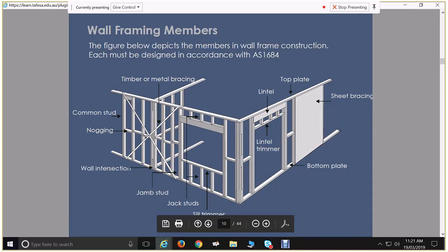Beyond that, then we have our bracing, and we've got two types of bracing shown in this. One of them is your galvanised iron strap bracing. You can buy 30 metres of that for about $10. So it's really cheap stuff to buy, a little bit time consuming to install, because you put it over the top, shoot some nails in, and then you put it down the bottom, and then take it over the top, shoot some nails in. While you're stretching it, you put your claw hammer in, you stretch it over to get a bit of tension in it, and then you tension it up with your little tensioners that go in there. So it takes a little bit of time to put in there. That will give you between 1.5 kilonewtons and 3 kilonewtons of restraint per linear metre of that bracing.